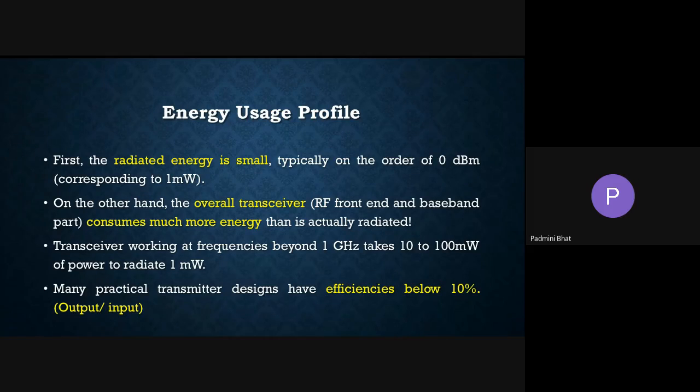The same medium, that is the environment, is used by another person, but he is using super high frequency, SHF. Because his frequency is different, maybe he is able to transmit 15 kilometers without any repeater in between. So these are actually channel modelings. I should find out the losses in the channel per kilometer, or per mile, per meter, how much is the decaying.